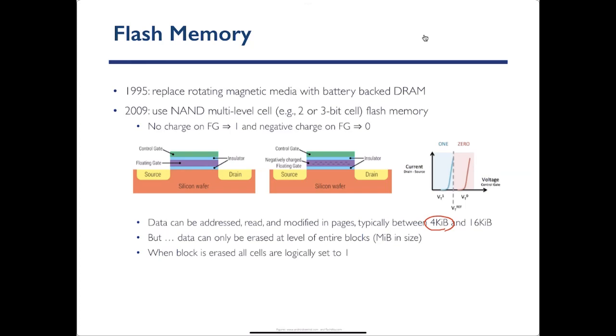As a reminder, with magnetic disks, the unit of data transfer was the sector. Here, the unit is the flash page. Reading data off of flash is pretty straightforward and easy, and you can do it with low power. It's kind of just reading from a transistor, so it's quite straightforward, fast, easy. Writing, however, to a flash cell is not that easy.